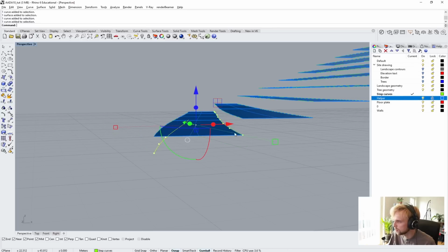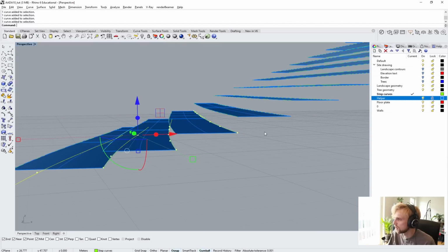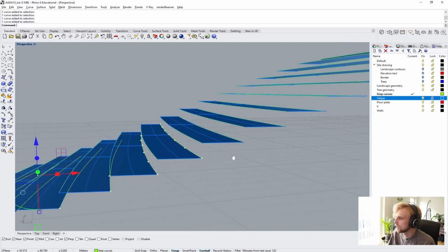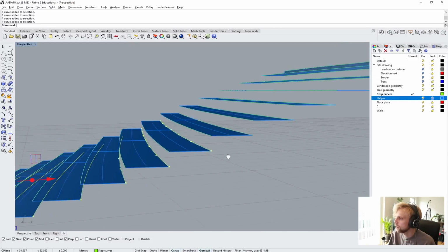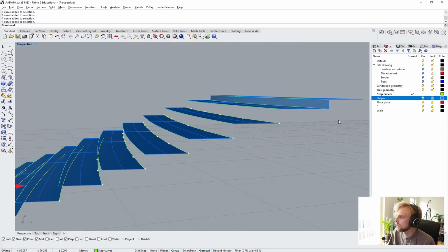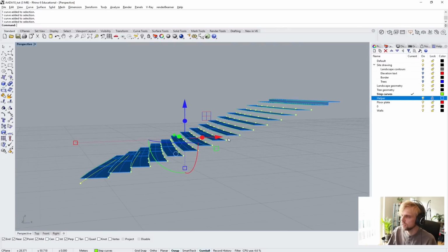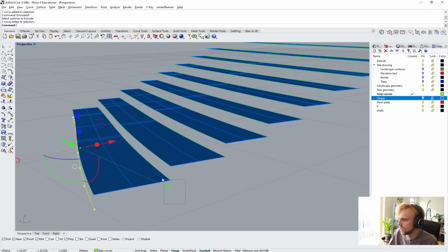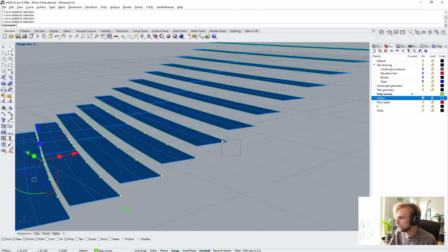This will just help me select the correct curves. So I just select the ones that are in the bottom, like that, and those are fixed. And then I just extrude surface, crap, not extrude surface, oh no, I need to select them again. Extrude curve, not extrude surface. Let me select them again real fast.